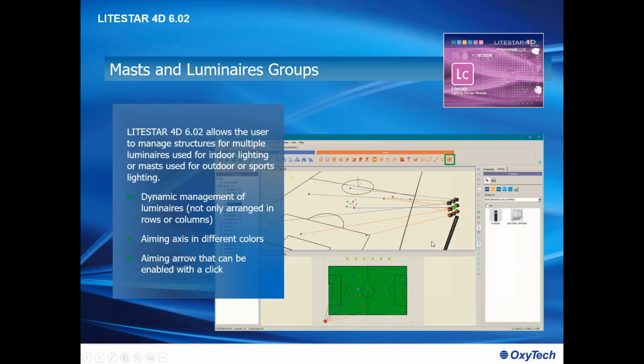So yes, we can leave them per rows and columns, but we also introduce the dynamic way, which means that you can move the luminaires in order to correspond perfectly to the situation you are finding. For example, a high mast may have different levels, and asymmetric luminaires cannot be placed exactly along a panel. Why? Because the luminaires above can be shadowed by the luminaires below, and so you have to move them a little bit farther out so that the light can reach the field.